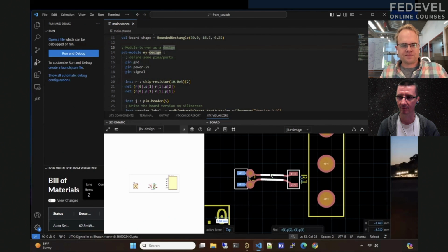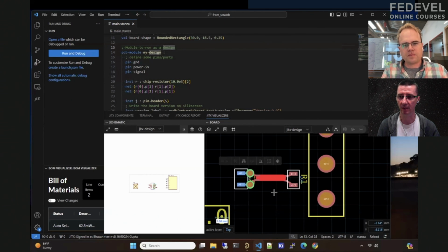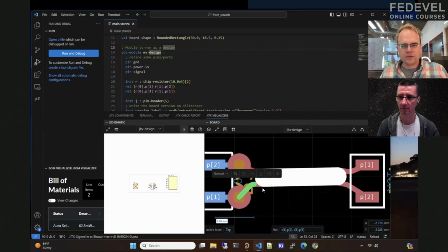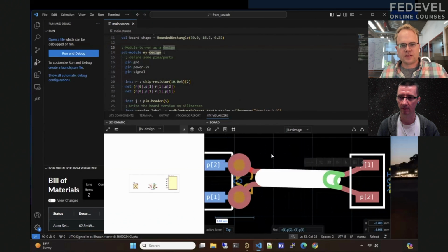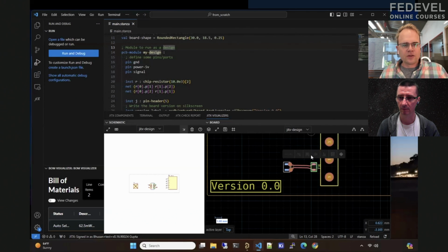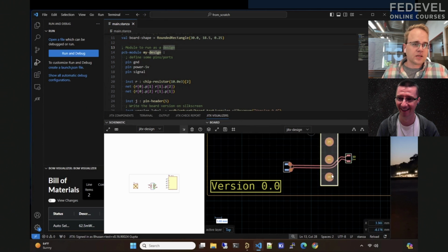Oh, I know what's going on. Hang on. So the model here is you select, and it's very fan out based. You do some kind of fan out because it's a differential pair. So the model is you fan out to your insertion point here. It's become a little hard to touch. There it is. And then your fan out moves with your components, so the pair will adapt as you move it, which is nice.